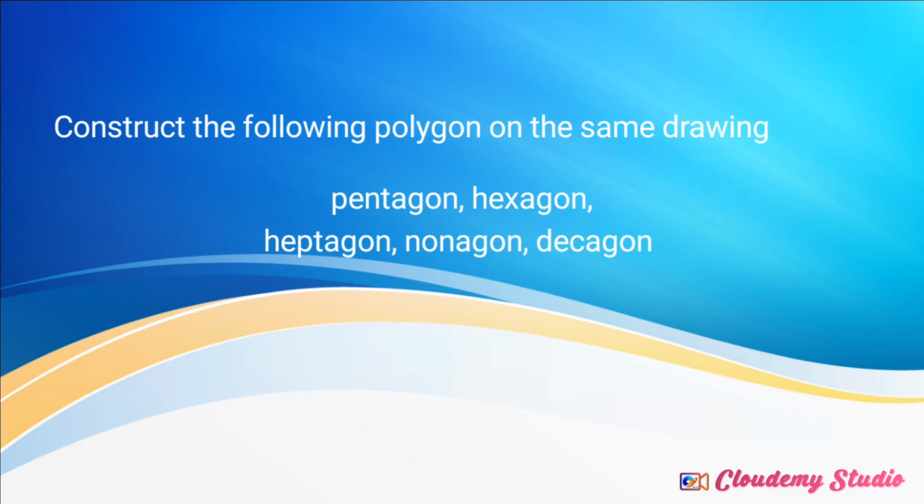So the circle is your first marking point, because whatever the examiner is trying to test you on, you make sure that the regular polygon is inside the circle. For this case, the question was, you have to construct a regular polygon, but you are given the length of one side. So you are not supposed to use the procedure for the length given the radius, because this one was to test if you know the procedure on how to construct any regular polygon given the length of one side. And I gave you this procedure because it applies to all other regular polygons.